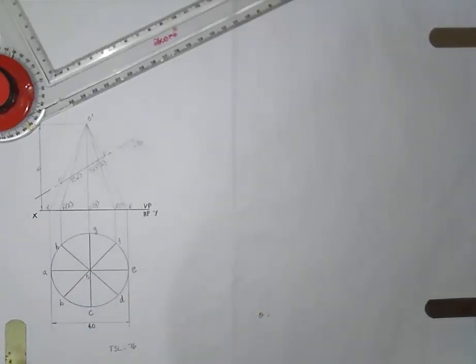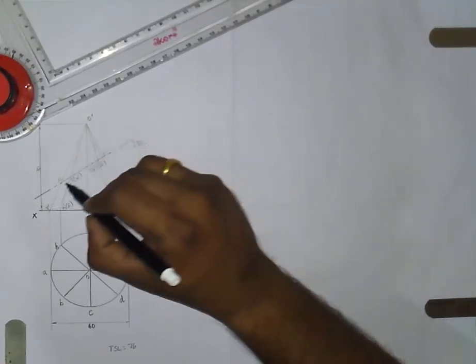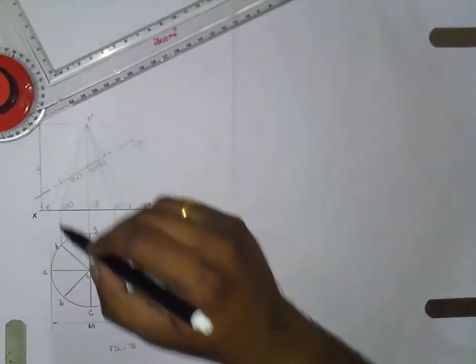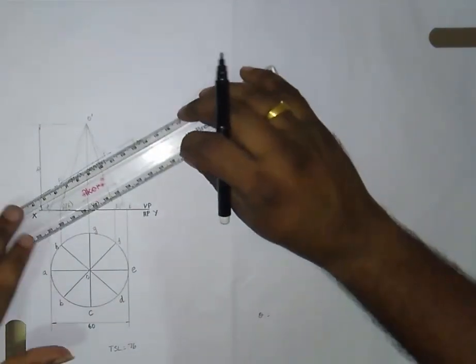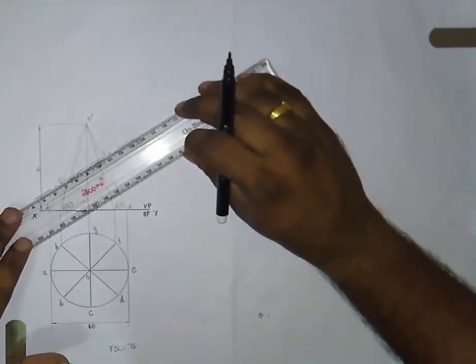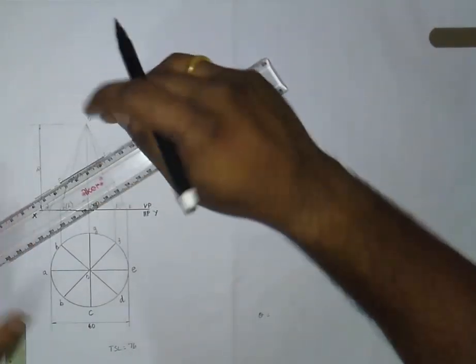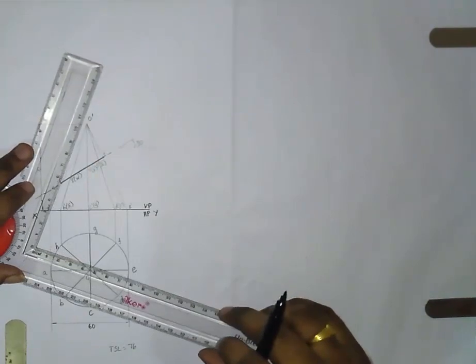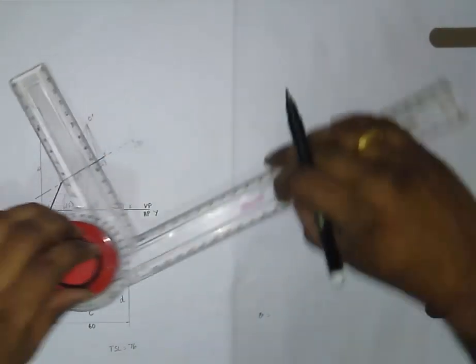Now we will complete the front sectional view. So in this portion, this entire portion gets removed and this portion will be the remaining portion. So that is the retained portion. So what you have to do, you have to draw the outer edges with H pencil in order to show the retained portion, that is your front sectional view. So this is your front sectional view.